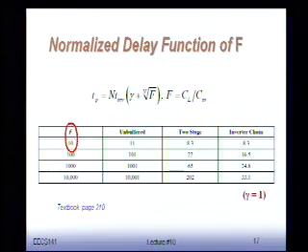So if I would take no buffers, so I just take a minimum inverter driving that capacitor which is 10 times larger, then we know that the propagation delay is going to be 1 plus 10, because f is 10 of that stage, so it's 11 times t invert. Okay? So the unbuffered delay in this case will be 11 times that t invert factor. Okay? And there's only one stage.